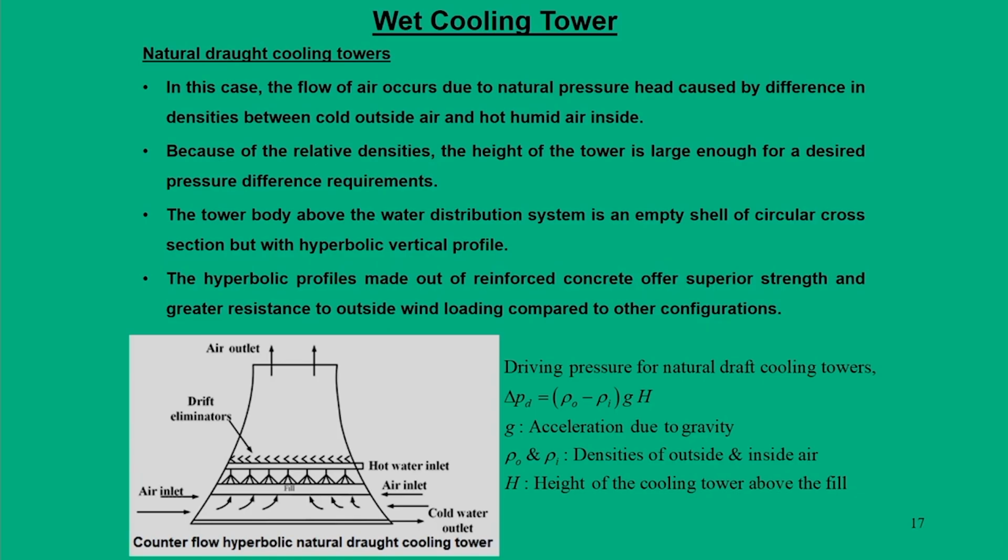apply here. So, what do you take advantage of? To take the advantage of this driving pressure as a density difference. So, in other words, you use the concept of raising the height of the tower in such a manner that in a tall tower we can get the advantage of the density difference of atmospheric air and the pressure inside this cooling tower.